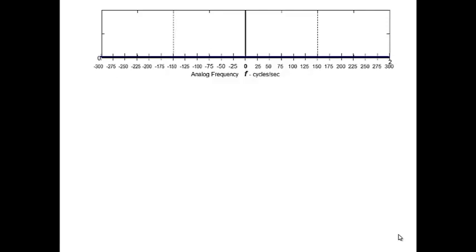Let's start with simple. What's the Fourier transform of 1? One at a time to me. What's the Fourier transform? Delta of f, an impulse in the frequency domain at frequency 0. And if I scale it by 2, the Fourier transform just scales, giving a weight to that delta function, right? All right, so we've got the 2 handled.